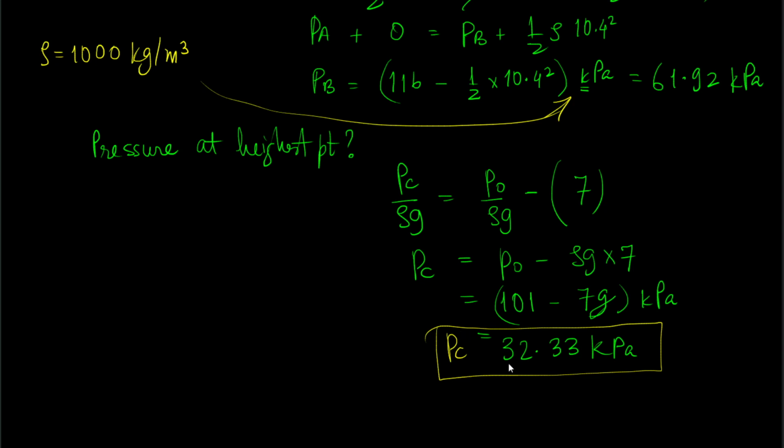If you keep the pressure throughout the circuit higher than the critical pressure, which arises due to considerations of solubility of dissolved gases in a fluid or the vapor pressure of the fluid itself, you're in the green. Otherwise, you have some issues pertaining to cavitation. Remember this while designing any hydraulic circuit.